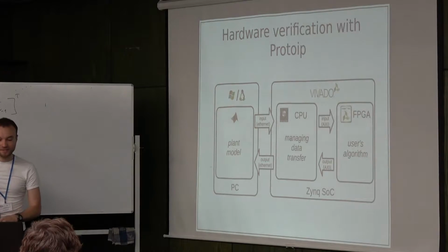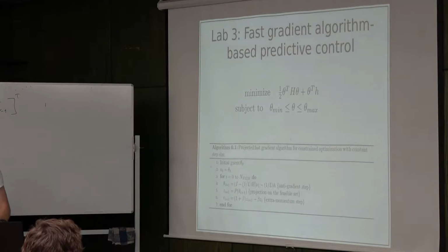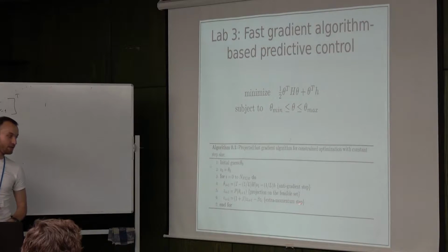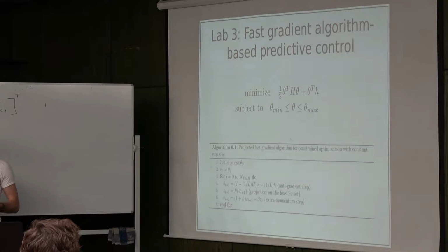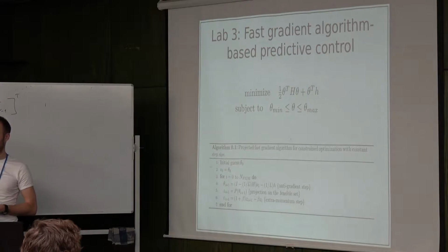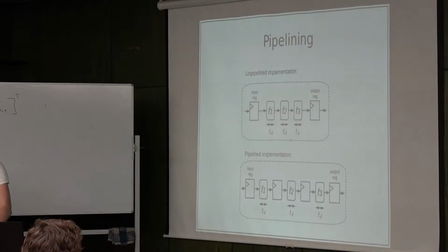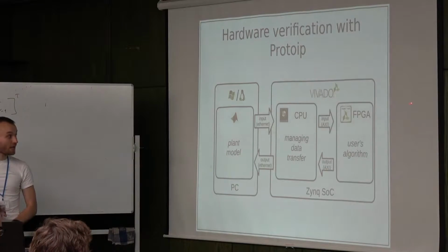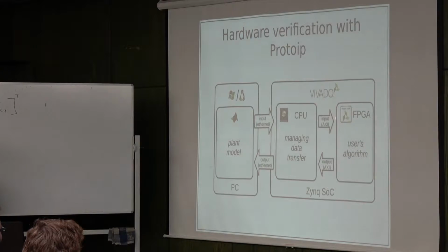We already understand that implementing even this simple algorithm in VHDL is not that easy. Even integer addition requires some effort. But when we come to fixed or floating point numbers, things become even more tricky. So that is why we use a higher level approach. We use another software tool from Xilinx known as Vivado HLS. This is their logo. You might find this logo on your desktop.